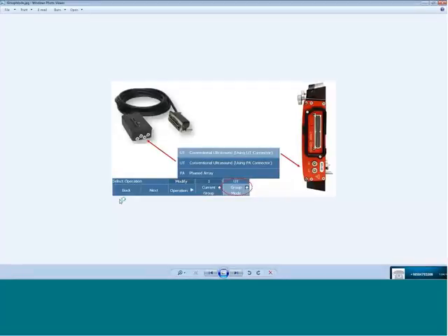The options that you see are either for the UT conventional, directly in a LEMO connector on a compatible module, UT conventional using an adapter through the phased array connector, and in this case, we would be borrowing 1 or 2 of the 128 available pins from the phased array connector. So this would typically be 63, 64, 127, 128, or a pure phased array group.